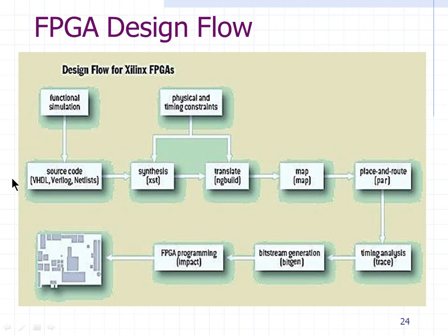Now, once you write the Verilog code for that block, you need to test whatever you have designed. For that, you need something called a test bench. A test bench is also a Verilog file. The design will be in Verilog and the test bench will also be in Verilog, and you will use this test bench to test your design. And you do something called simulation. After simulation, you'll generate timing diagrams. The timing diagrams will tell you whether your design is working correctly or not. If it is not working correctly, then you have to fix your design. And this is an iterative process.